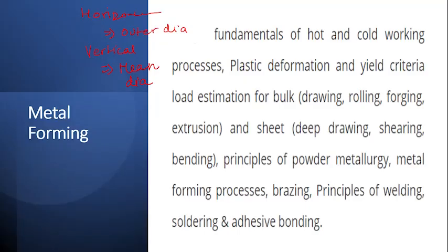The second doubt was with the riser: when to take the bottom surface and when not to. If the question mentions that it is a top riser, then you don't have to take the bottom surface of the riser, or starting surface.